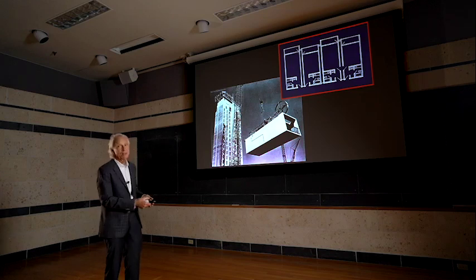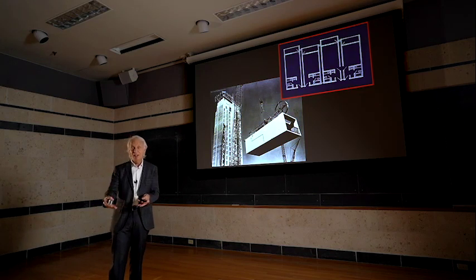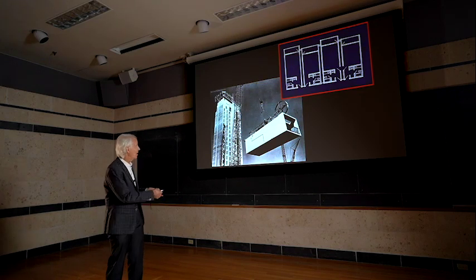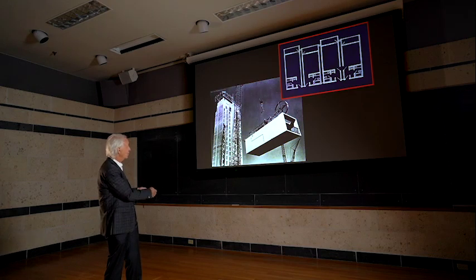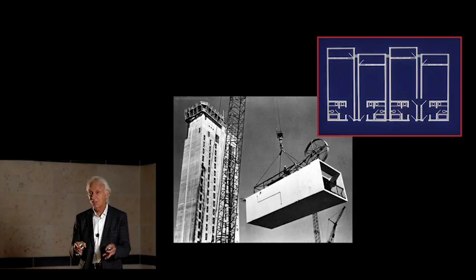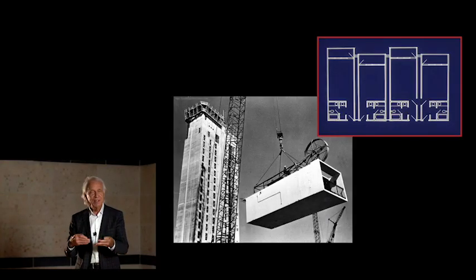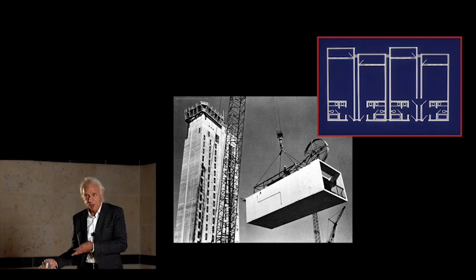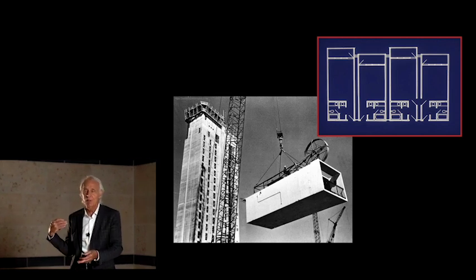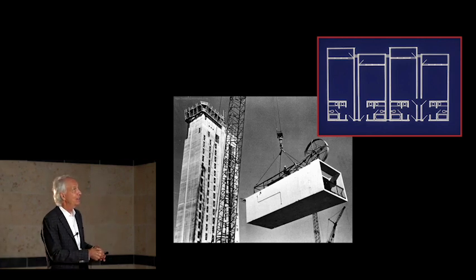In the meantime, they'd been doing the site work and the foundation and the core of the building where the elevators would run right there. And then they're prepared to then bring those boxes out and stack them up. But now we've shortened the amount of time by doing the site work and the foundations and essentially the structural system of the core, concurrent with, at the same time as they're already doing the finishes and the plumbing and all of that for the hotel rooms back in the prefabricated factory.